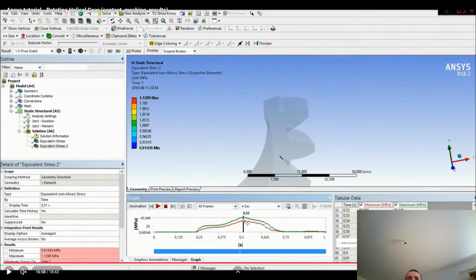Here, because he has these values and they should be 46 megapascals, we should right click and reset the legend, or yes, adjust to visible. Right click, adjust to visible, because the legend is not updated to what we see here in the graph.